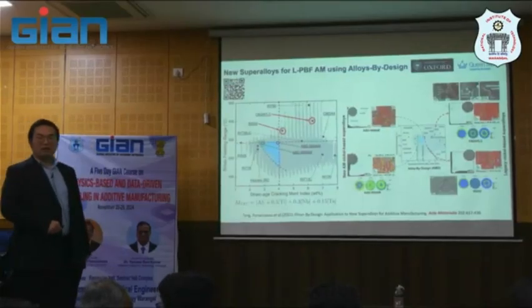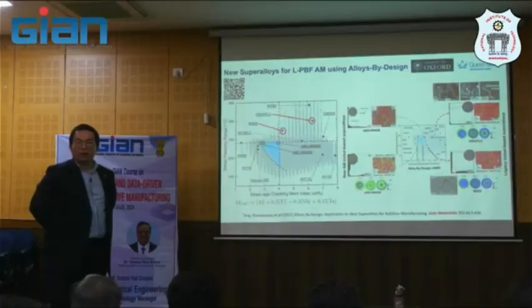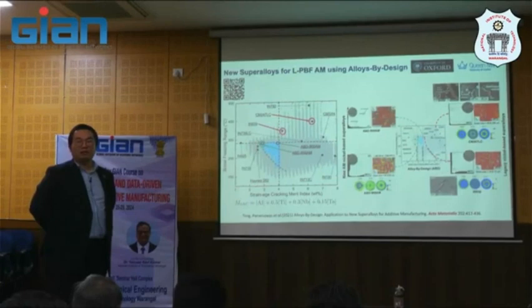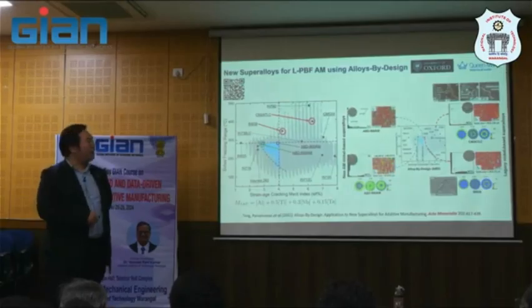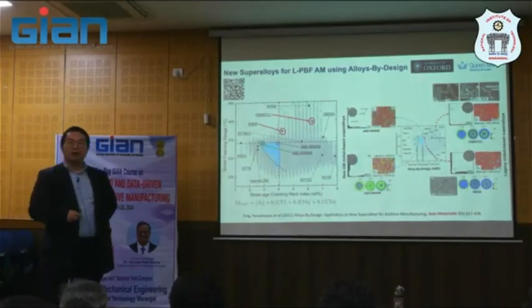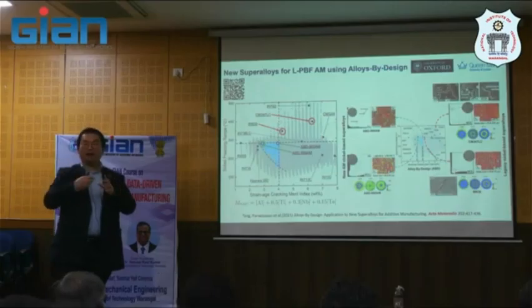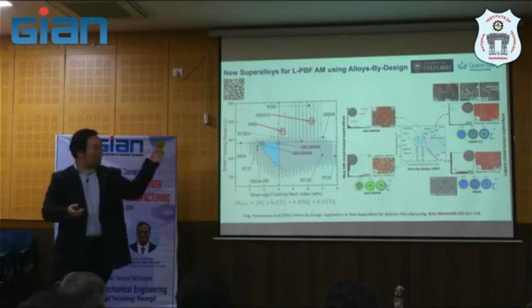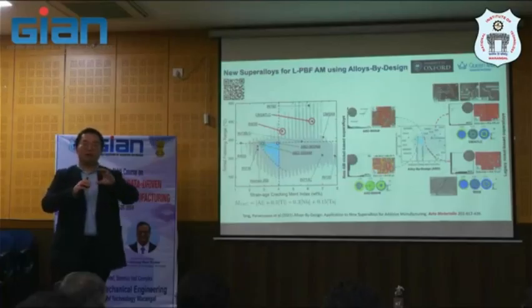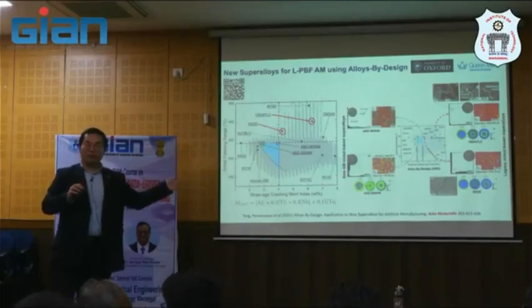So in the micrographs, they are solidification cracking. In the micrographs, a mixture, no. It will be ductility dip, liquation, lack of fusion. I mean, the crack here is hard to identify, because based on imaging, the crack in this sense means any line in the microstructure. We have not classified yet, because this is image-based analysis. It's not like tomography, where we can identify the feature like in the previous work.